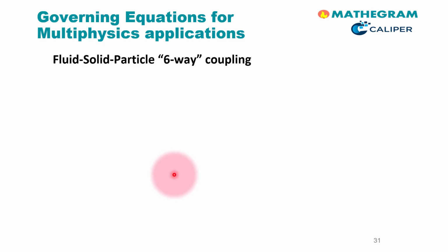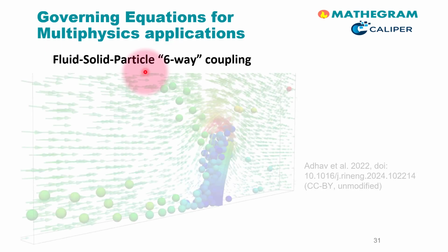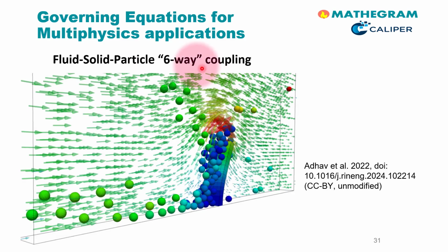This slide allows us to look at a situation in which we also have particles in the fluid. The authors call this a six-way coupling, since all interactions between particles, fluid and an elastic structure are considered and fully, meaning two-way coupled. As you can see, really complex systems can be modeled once we bring together the DEM with CFD and structure mechanics.